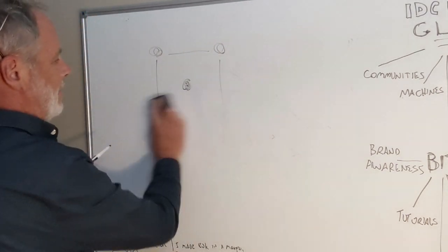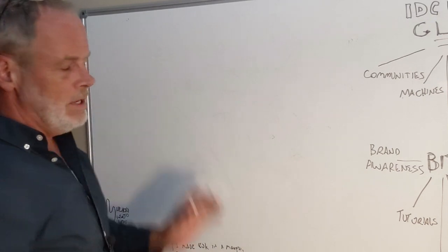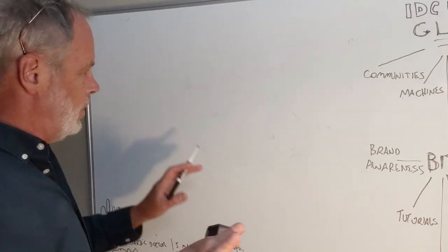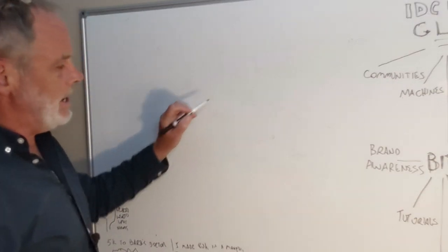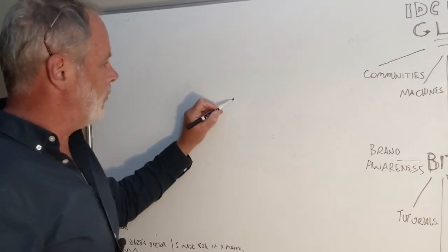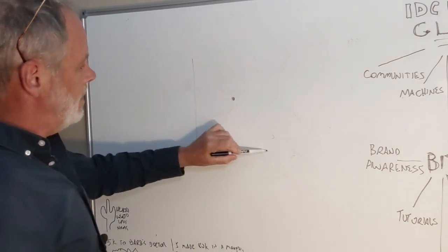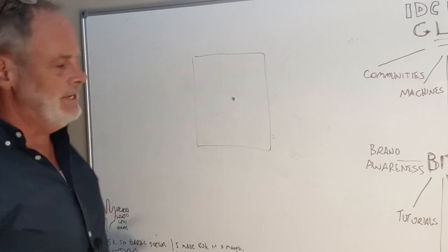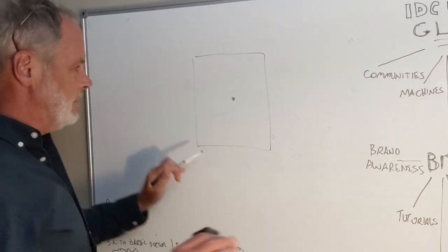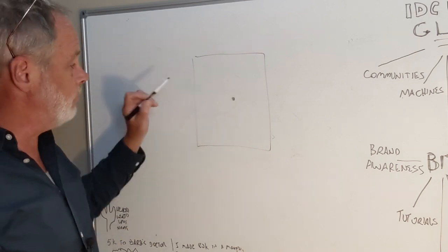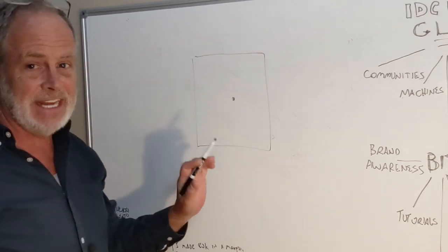So when you tell Vectric to create the rectangle in the way that I'll be showing you, it's going to say, okay, I'm going to build the rectangle from that dot. So that rectangle is going to be built around the dot just like you saw. This would be the actual rectangle that it draws in the software, but it's referencing the center of it.